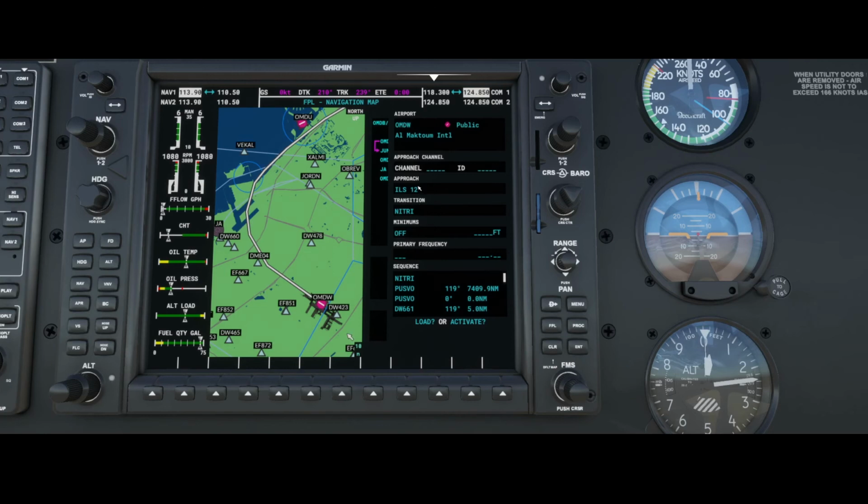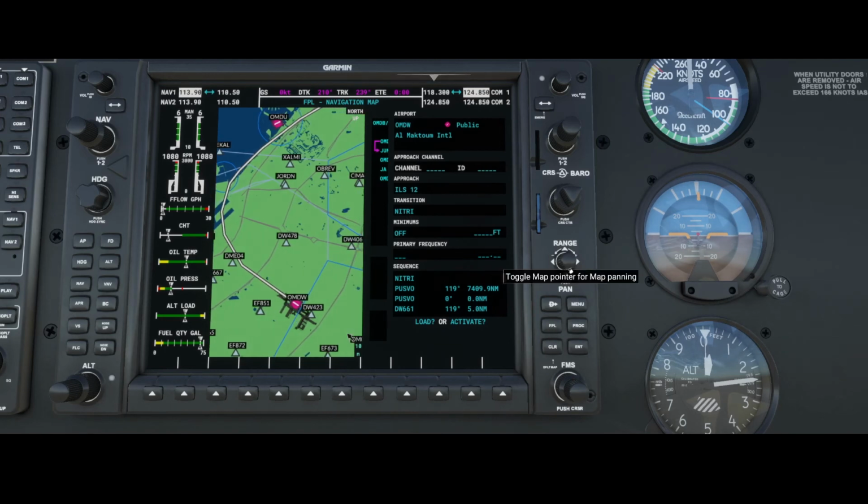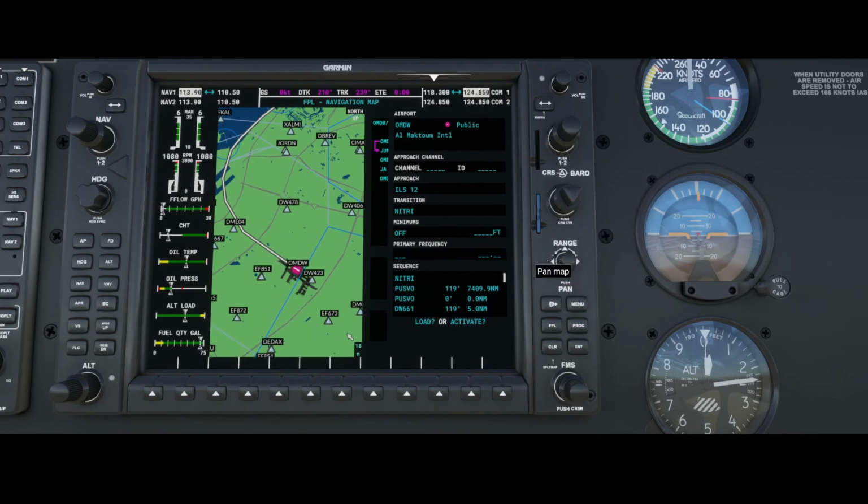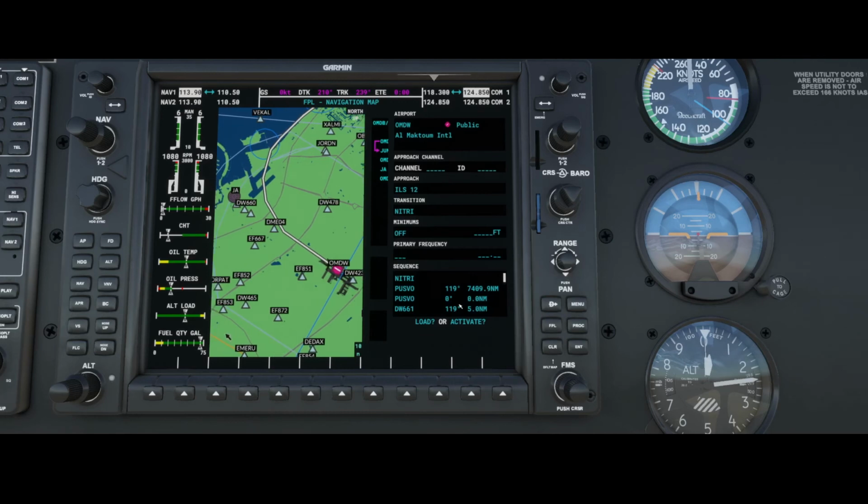And you can use the transition, and the transition means, okay, which transition are we gonna make? So which waypoints are we gonna visit before making the final approach? Those will also make sure that we are making the correct landing and we're correctly aligned to the runway. So what we can do is we can use this list, because this is the sequence of waypoints which we're going to visit, to make sure that we're taking the correct approach.